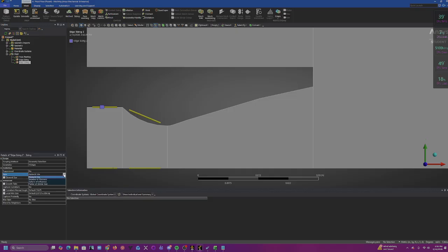And we want to change this to divisions. Number of divisions, we could put 50. And then we could change the capture curvature from yes to no. And then we can indicate it from soft to hard, that behavior soft to hard, pause. And then we're not going to be adding a bias, so we can leave that alone.